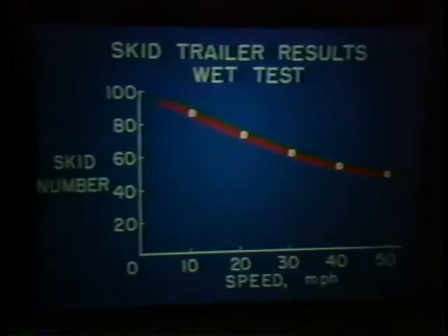The likelihood of skidding increases with higher speed of travel. So the surfaces of high-speed roadways need to provide friction for the increased speeds. In addition to texture, adequate cross slope is needed to drain water from the pavement surface. Cross slope also affects steering. In road construction, the design values of the cross slope should be followed closely to balance drainage and steering problems. Too great a cross slope creates steering problems. Too little a cross slope doesn't adequately drain the surface.